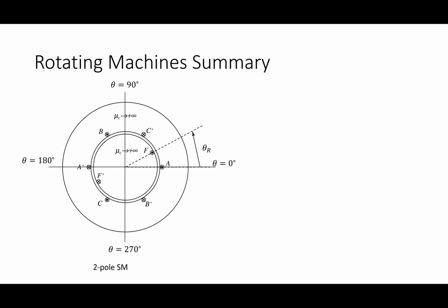All right. Synchronous machine versus induction machine. Synchronous machine, this is our two-pole machine. Put a DC current in the field coil, three-phase voltages on the stator coils. The key thing with this one, for it to produce torque, what had to be true about that field created by the stator and the rotor speed? They have to be synchronized to each other.